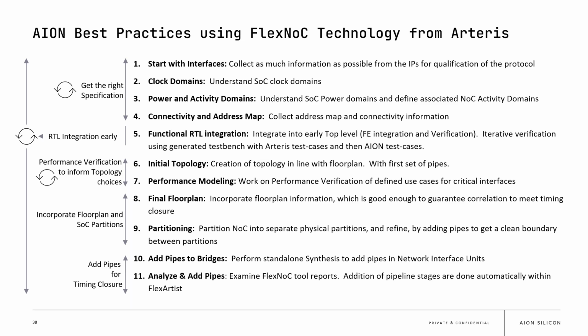You want to start this early because that ensures your integration team have a NoC to start integrating and make sure that all their flows are pipe cleaned. As the project matures, you might have different deliverables to different teams. So for example, you might have a different NoC to deliver to your FPGA team compared to your ASIC team. In addition to these, you also have deliverables to the verification team, as well as architects who want the system view of the NoC, SystemC view of the NoC. So all of these need to be managed.